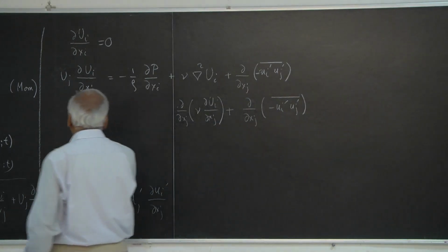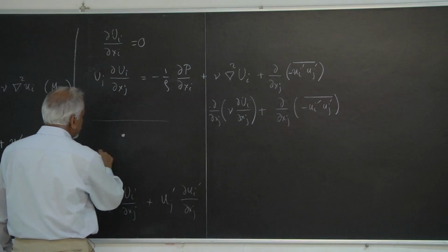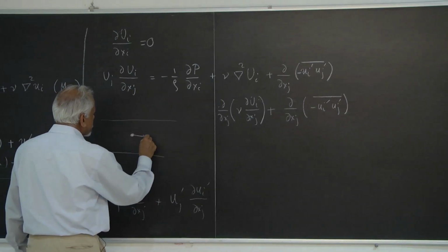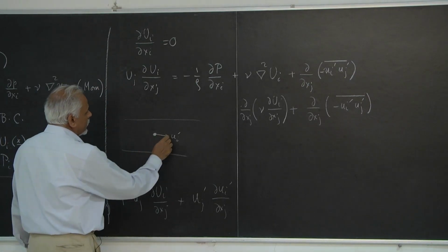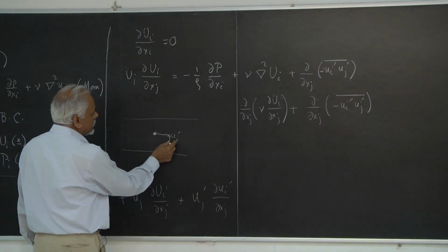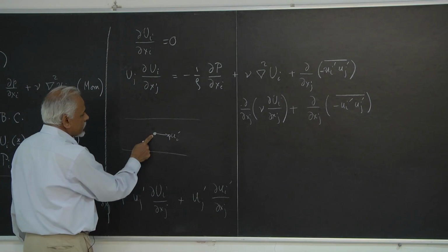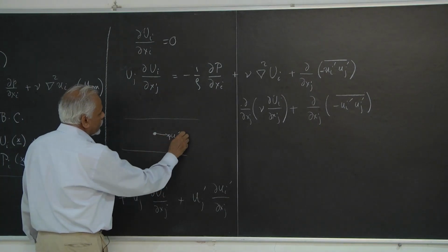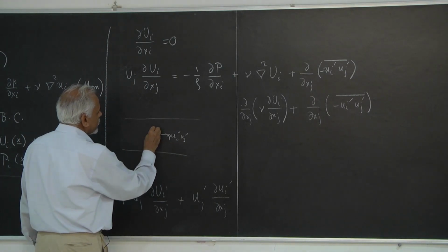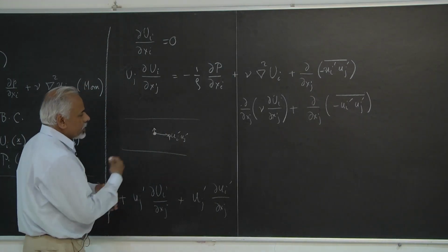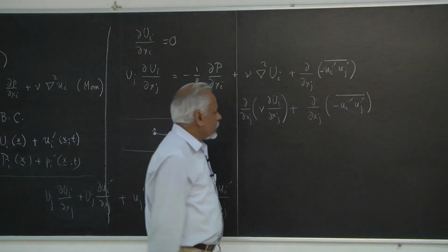So what this means is that, for example, in a flow like this, if I have a velocity of the fluctuation, which is ui prime there, and rho ui prime, let's say, is the momentum of a fluid parcel, and then you multiply this by uj prime, what it says is this fluid particle is moving to the neighboring layer, where in fact the momentum could be quite different.